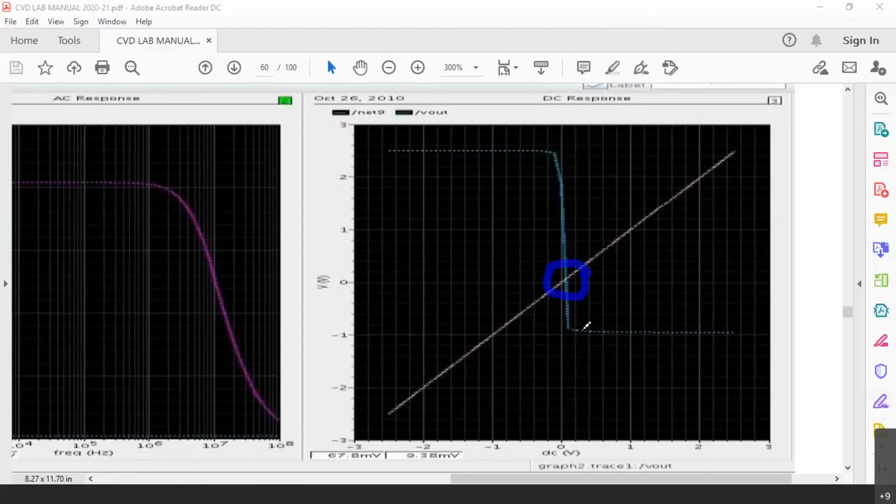Now if you want it to come down here, then you have to go for an op-amp only, which means op-amp should have a larger DC gain also. Right now we are working only with the DC differential amplifier. You have to connect one more amplifier at the output, where you should give a larger gain. When you give a larger gain, automatically this line comes down here. Otherwise, you can verify that in the DC analysis, output and input are out of phase. When input is increasing, output is reducing. That way, this particular input is the inverting input.